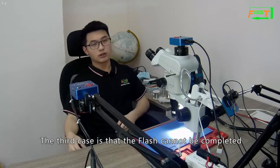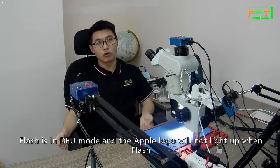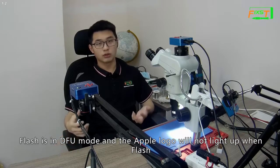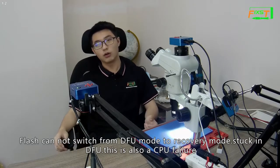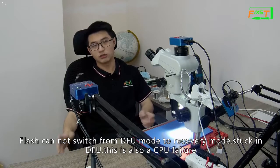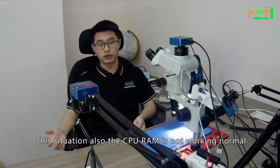The third case is that the flash cannot be completed. Flash is in DFU mode, and the Apple logo will not light up when flashing. Flash cannot switch from DFU mode to recovery mode. Stuck in DFU. This is also a CPU failure. In this situation, the CPU RAM is also not working normally.